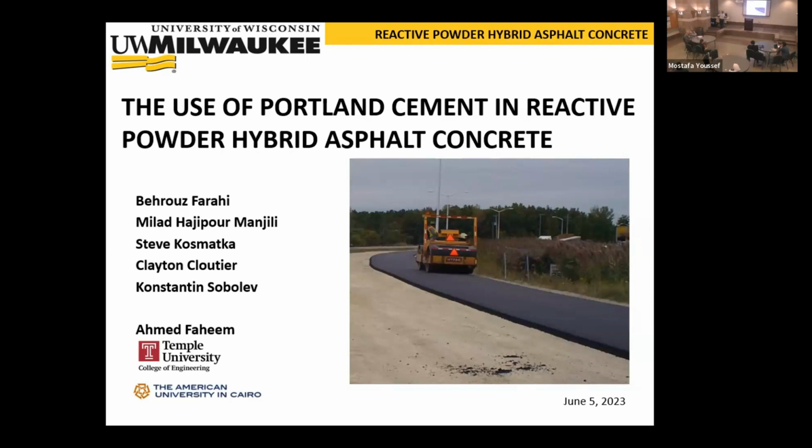In this work we compared manufactured limestone powder, because common asphalt technology would include a baghouse filter, which is an uncontrolled powder mix, variable, and gives variability to the mixtures. So this is the importance of what we need to modify.